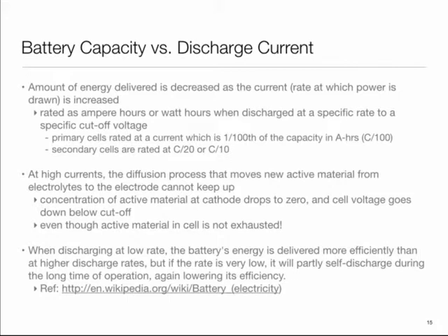What do you think leaks more, batteries or capacitors? Does the leakage depend on the amount of time? Like, does it leak more if it's... Sure. I mean, leakage is a current, right? So to the first order, you can model it as leaking at a particular rate. Okay, the leakage current is going to depend upon the voltage. It will depend upon the current state of the battery, but there's basically some leakage current. So yes, you integrate that over time to say how much energy we have lost. Okay. Huh? Yeah, capacitors leak more, unless you cut them off from the circuit totally.